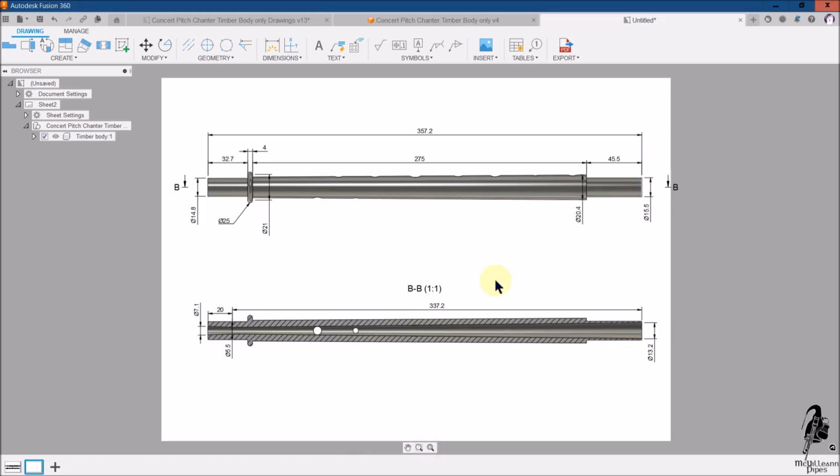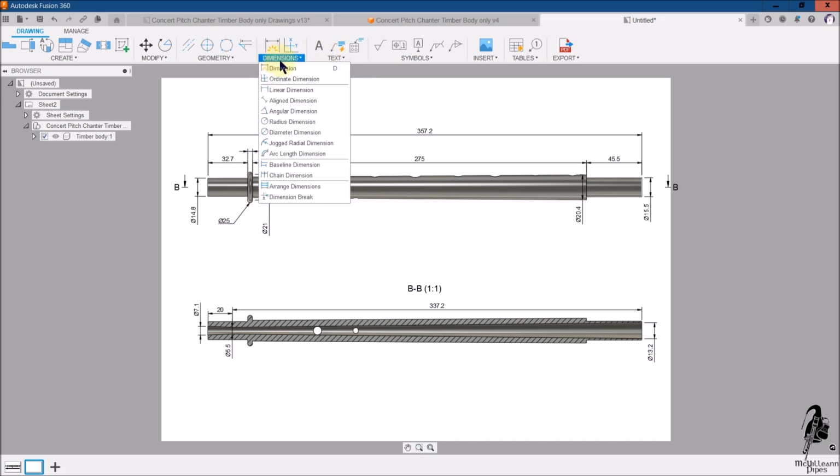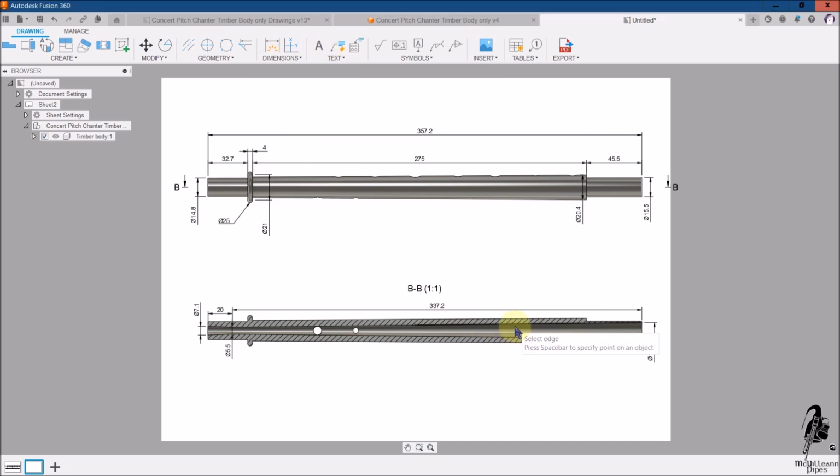We zoom back in. And we go back for angle. Now, if you see here, you have the green square showing up. If you leave that showing up, the angle will show outside. You get the cursor in so that there's no green square at all. Come down, a green square pops up. I lose sight of the angle. I go back into the middle, no green squares. Click. It stays where I wanted it.